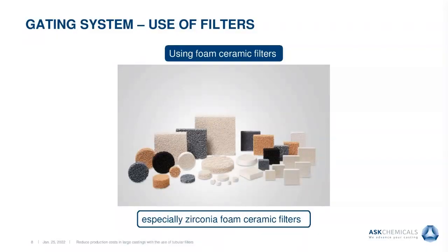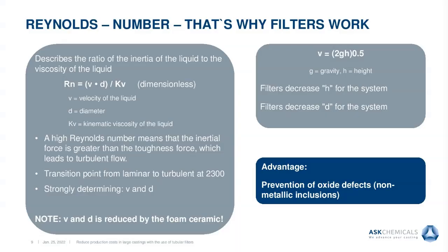Here, the filtration comes into the game. The filtration of different molten metals and their alloys is the state of the art today and daily foundry practice. Clearly, a lot of developments have been seen in the past. The development of ceramic foam filters made from zirconia is one of them. But before we switch to zirconia and ceramic foam and go a little bit more into practice, we also need a bit of theory on why filters work.